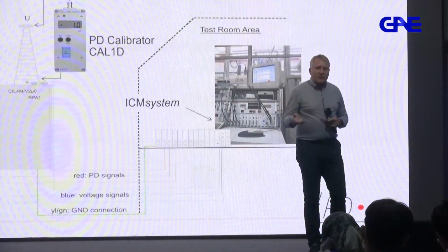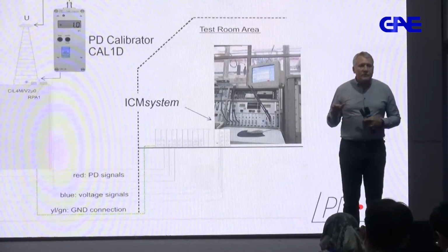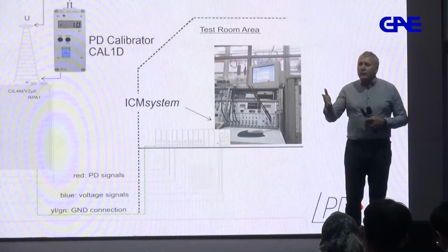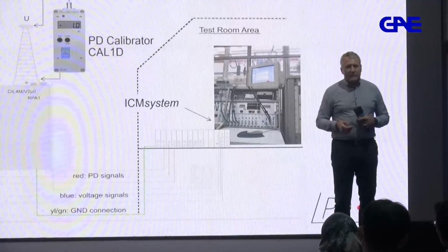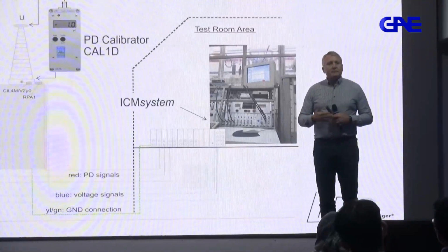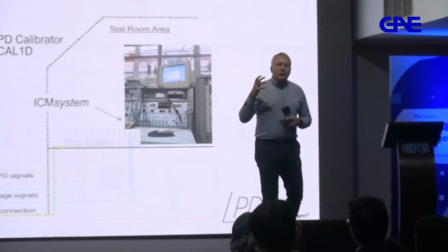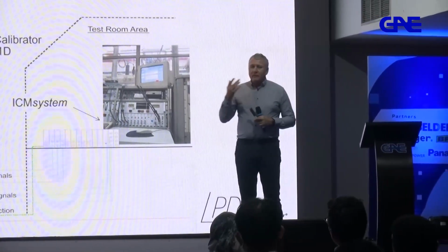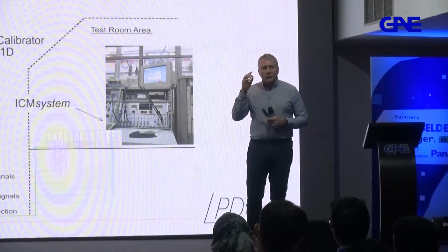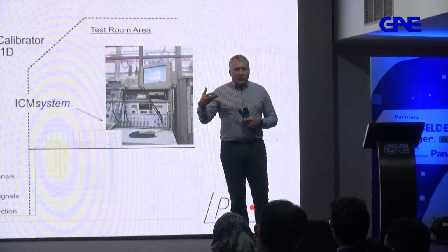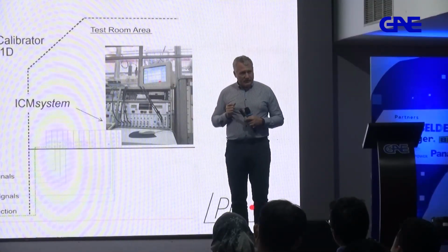So once the entire measurement channel has been calibrated, you will be able to do what is called, in the transformer business inside of the factory, the applied and induced voltage tests. How many of you are familiar with applied and induced voltage tests for power transformers? Okay, so I will explain that a bit also. So when you have a power transformer, from the low voltage side, you are going to induce into that transformer a certain voltage and make a record of partial discharge.